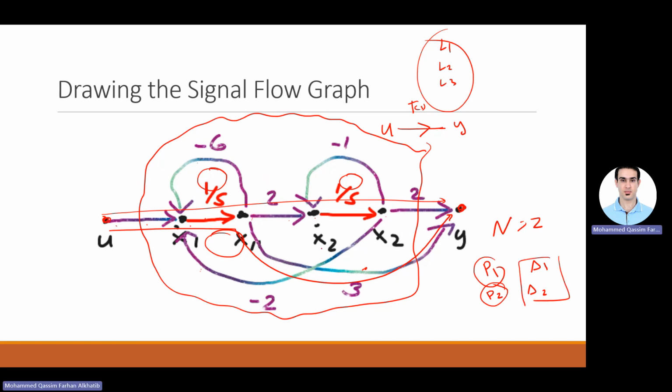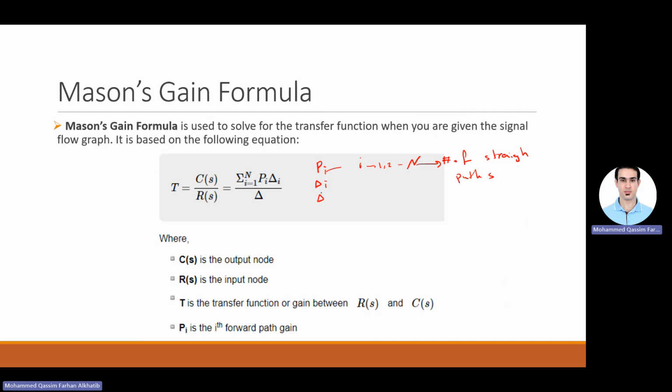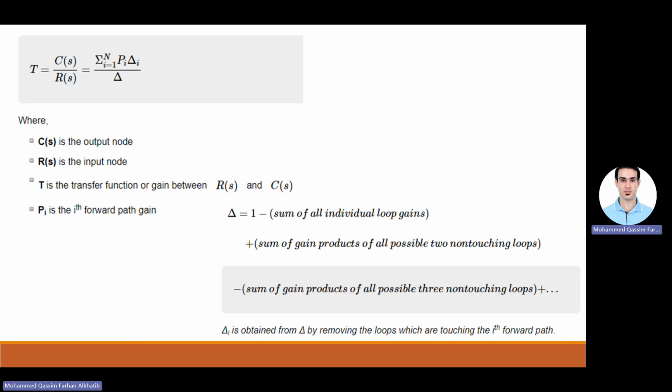Now these deltas can be identified by having this larger delta, let's say. This delta that does not have an index. And there is an expression to find this delta. All right. So this is the formula, same information from before. Now this is delta. It's going to be equal to 1 minus the summation of all individual loop gains. So previously, I have L1, L2, L3, summation.